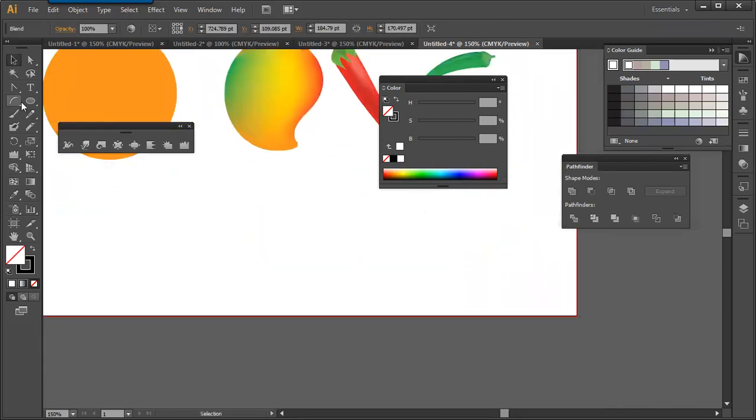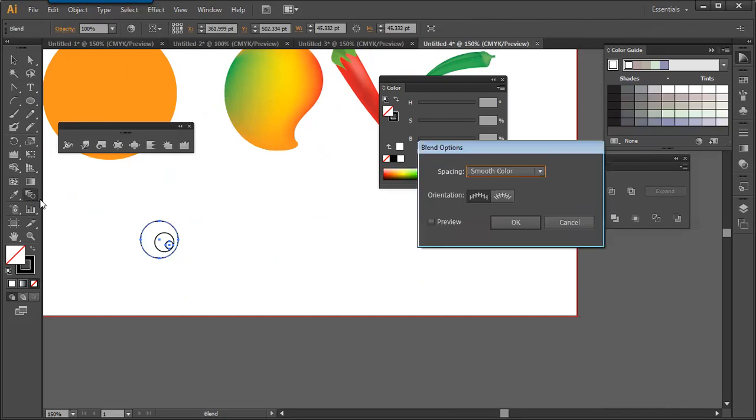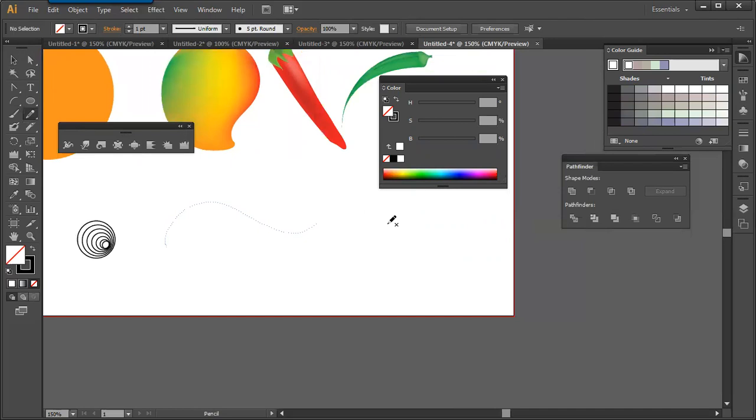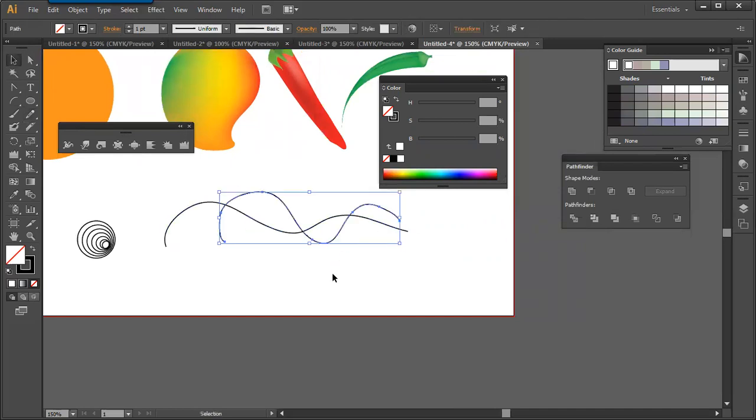It is not only the open set, we can work with the closed sets. Select these two, or else without selecting, click on the first object, click on the second object. The middle object happens automatically. Take the blend tool, press Enter, find the steps and modify them as much as you want and click OK. So closed blending, open blending, and open-closed blending are also possible, and an open shape can be done with anything. We can get a structure like this.